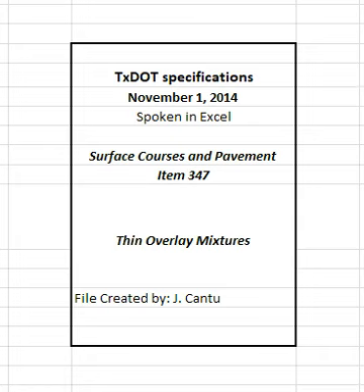4.4.2.1.15 Mixture production. Use JMF2 to produce Lot 1 after receiving approval for JMF2 and a passing result from the department's or a department-approved laboratory's Hamburg wheel test and the department's overlay test on the trial batch. If desired, proceed to Lot 1 production, once JMF2 is approved, at the contractor's risk without receiving the results from either the department's Hamburg wheel test or overlay test on the trial batch.